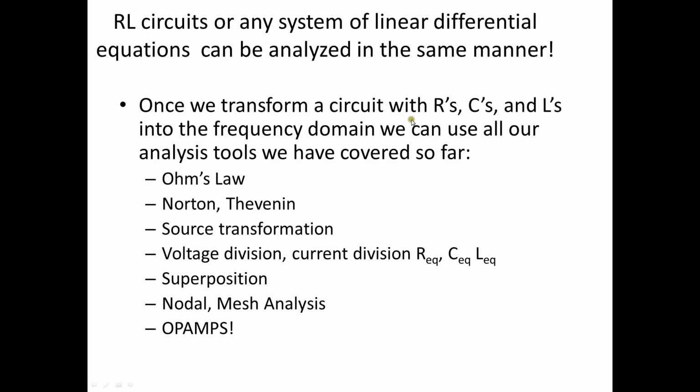And the thing is, once we transform a circuit with our resistors, capacitors, and inductors into the frequency domain, we can use all of our analysis tools we've covered so far, such as Ohm's law, Norton and Thevenin equivalence, source transformation, voltage division, current division, resistive equivalence, capacitive equivalence, inductor equivalence, superposition, nodal, mesh analysis, and op amps.